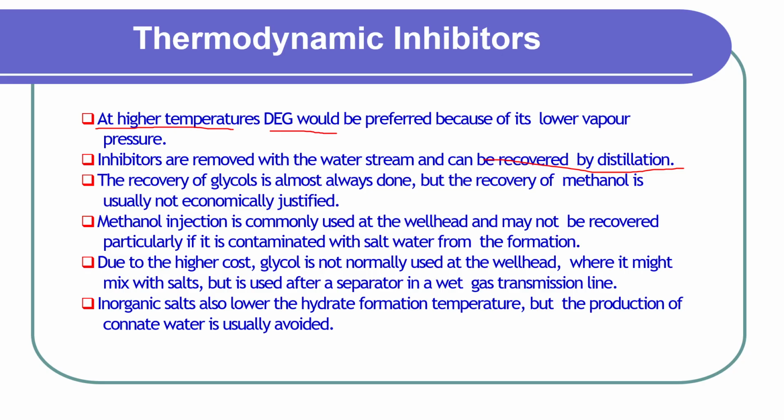And why is that? Because, as you know, methanol and water are highly miscible with each other, which means that they like each other, so it's very hard to separate them through distillation. You need a much more complicated process to separate them, so it's not viable most of the time to separate the methanol from water.